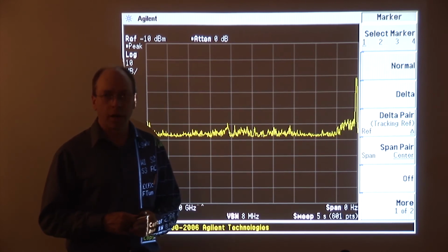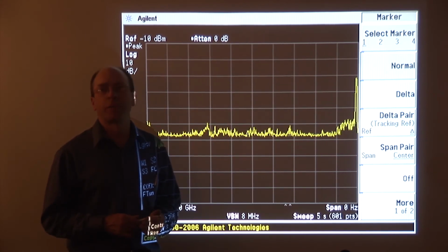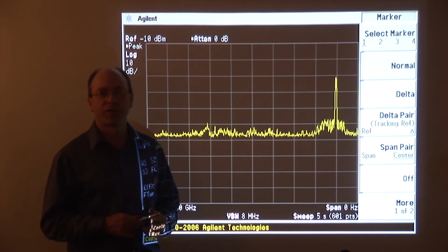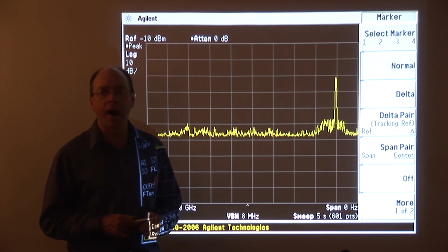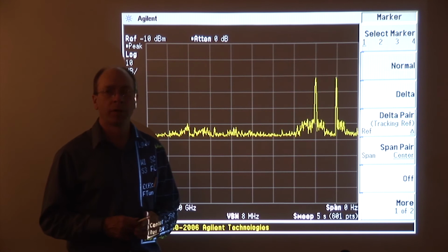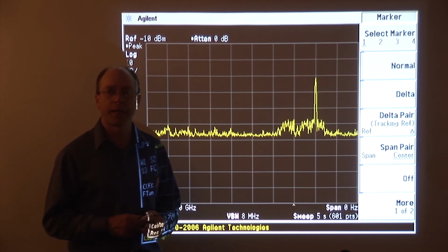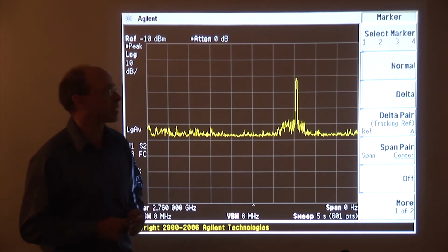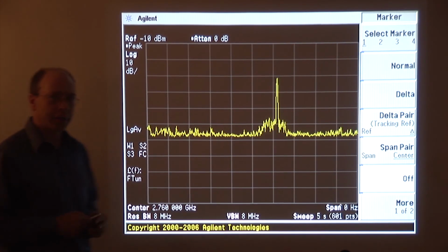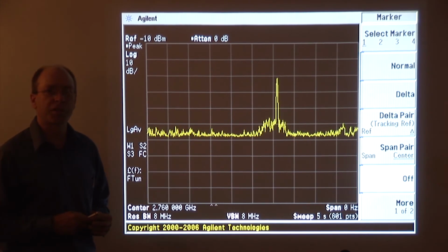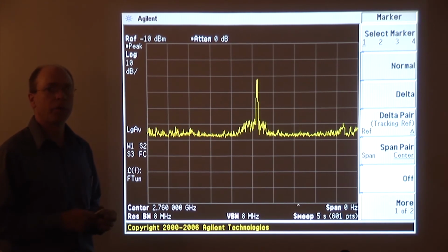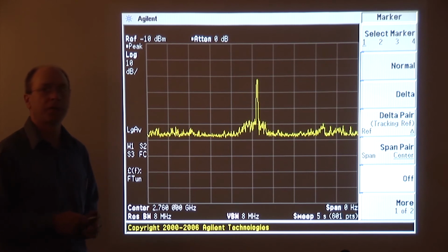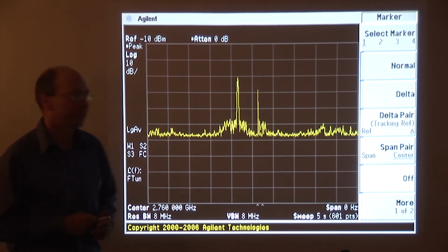In this part of the talk, we're actually measuring emissions from a radar that's located roughly 30 miles from our lab. So this is not an optimum location for the measurement, but it will demonstrate how we get the data. We're actually using a cavity-back spiral antenna in a window of our lab building about 20 feet away from where I'm standing. And initially, I'm going to show you what we see on a spectrum analyzer display. We'll then transition into the use of the computer-controlled system.